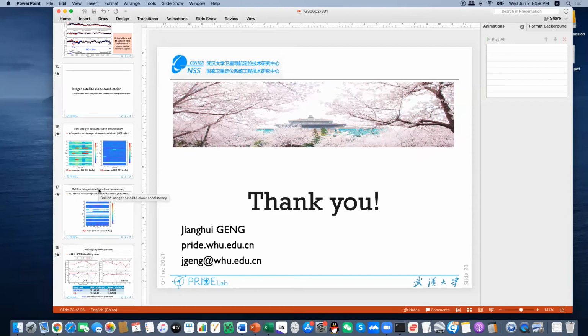I think this is a very interesting question, though it's not relevant with my slides. But anyway, this is a very important question in the engineering applications for PPP AR. If you have the atmosphere constraint for the PPP solutions, you can certainly improve the resolution of the narrow lane ambiguities. And then you can achieve the ambiguity fix solution within maybe a few seconds.